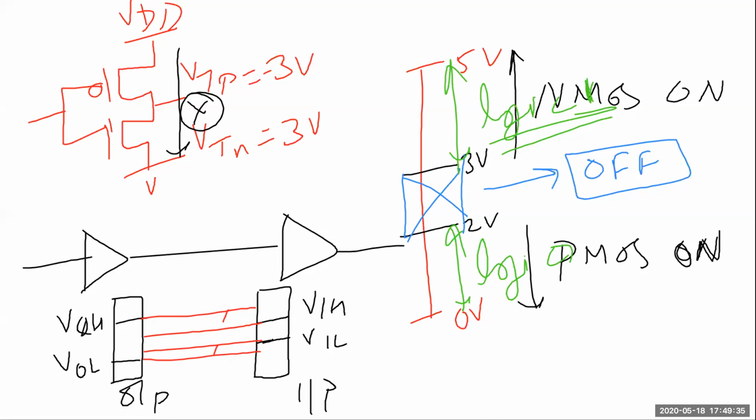Oh, hold on a second. Actually, both of them are at VDD. So this is on, so this is 3 volts. So till 2 volt, it can come and go. I guess it becomes a dynamic logic. It'll hold the value, but I don't know how they will define it. Basically, your output should not change when it goes from 5 to 2, which I don't think it will, but it is actually a dynamic circuit now.